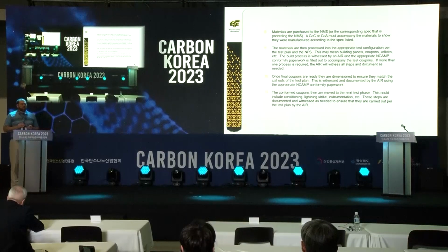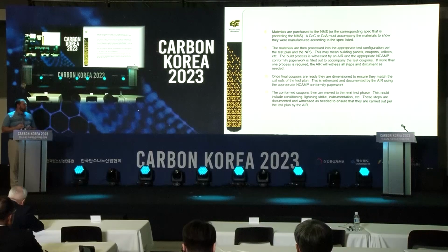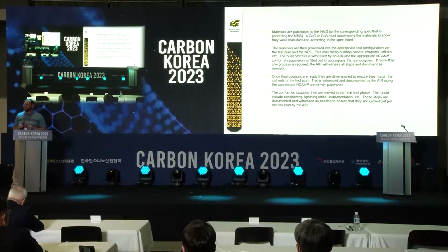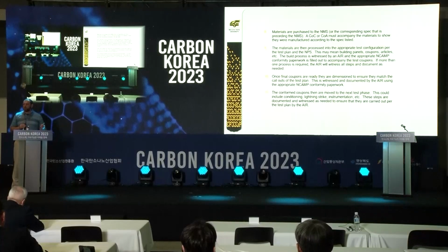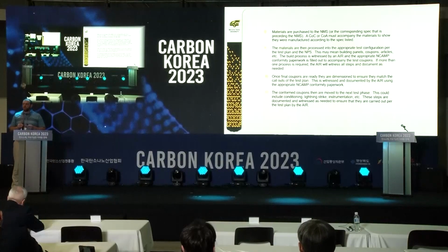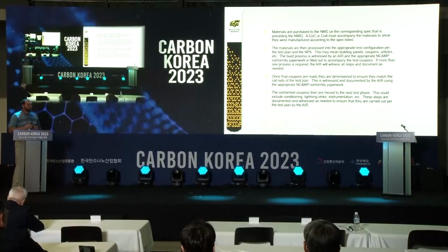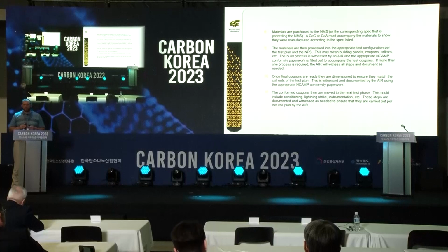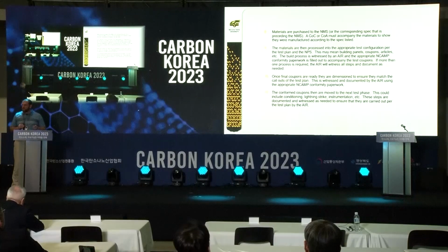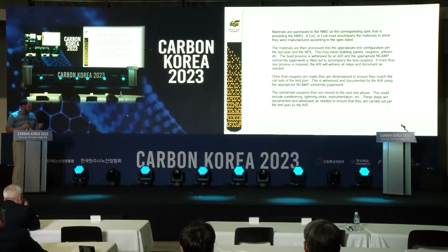Once the materials are produced for the qualification, then they're moved into the testing area, and they have to come to the test facility with some sort of CFC or C of A that says, yes, they were produced correctly, and yes, they were purchased correctly, and yes, they are stored correctly. Once that's done, they're created into either panels or coupons, billets, whatever is needed per the process specification. And then from there, created into coupons. Those coupons are then conformed by the AIR, the Airworthiness Inspection Representative. Again, another step in the conformity process to make sure that everything is done correctly. Once that's done, then they go to the testing phase.